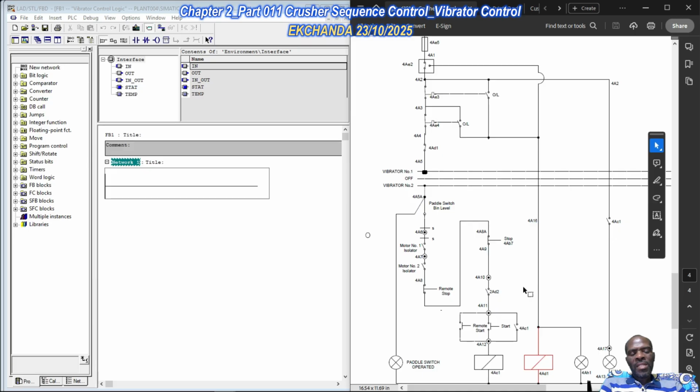It's not an actual operational state that has caused the input to change its state. Say a loose wire or some machine shakes, then the system gets into this faulty state, and even after everything normalizes, it gives you a pain just to try to resolve that issue. And when we did that, we were latching all the input conditions. We are just purely latching them.